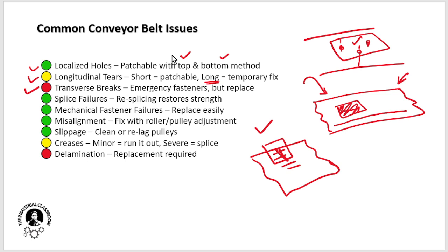So here, generally, fasteners are put, but depending on the case, if 10% is cut, then we will generally repair it. If more than this is cut, then we must change it, because for an emergency we can use a fastener, but it is not a permanent fix.